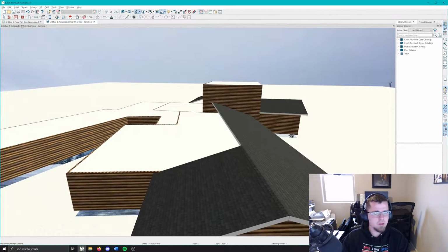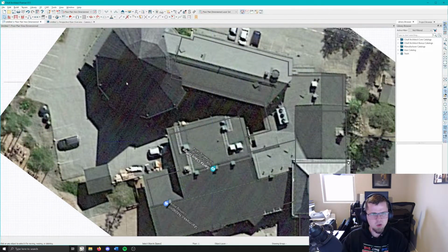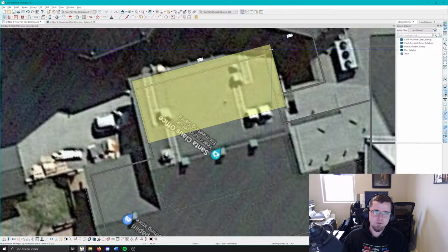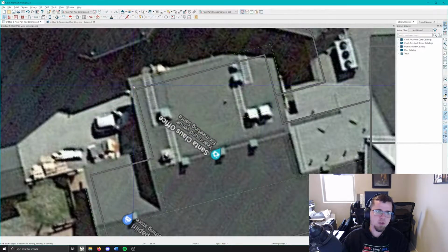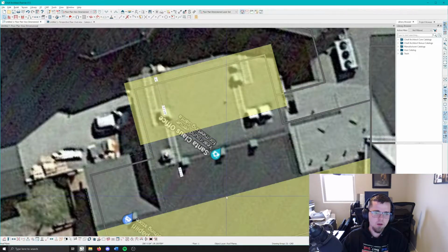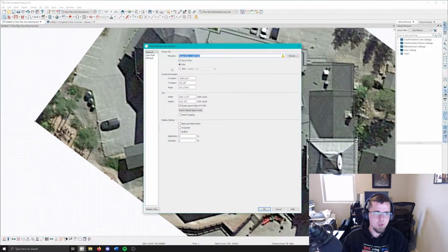All right, so this is going to come out. It looks like it's centering right in the middle. I was trying to figure out if it was a taller ceiling in here. I don't think it is, just longer. So we'll go ahead and draw this over. I'm grabbing the edge of these roof planes. You can just faintly see the green dotted line. I'm grabbing those to adjust the roof plane edges.